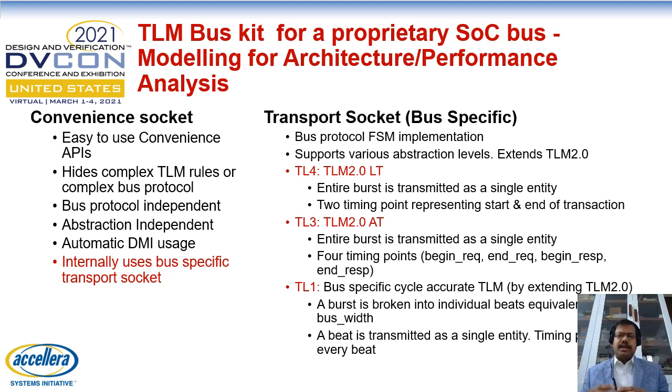And here there are a couple more things to understand. So when we talk about transaction level modeling, it describes broadly two kinds of models: a loosely timed model for fast simulations, and an approximately timed model which is transaction level accurate and which is used for more detailed modeling requirements. Similarly, the OCP-IP consortium has defined 5 levels of abstraction ranging from TL4, which is the most abstract, to TL0, which is the most detailed level of modeling which matches the RTL behavior.